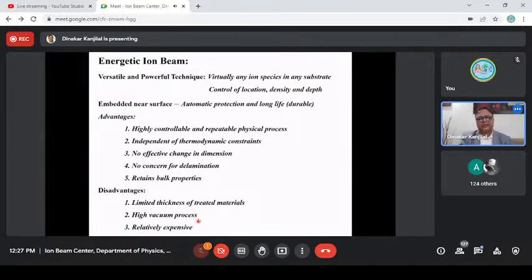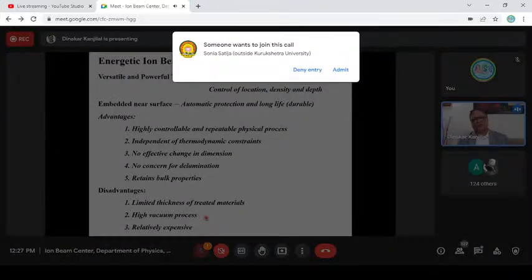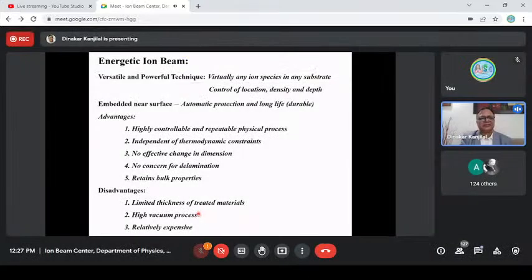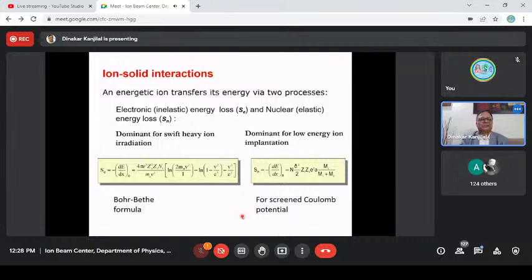Why high vacuum? Because you have seen clean rooms. Clean room means you will see sometimes 10, 100 particles in a particular cubic meter volume. Here, cleanliness is even a fraction of one, because in a very high vacuum there are no atoms, 1 in comparison to atmosphere, 1 in 10 to the minus 12, minus 11. So this is the cleanest room, the cleanest environment, vacuum, where you are making your processes.